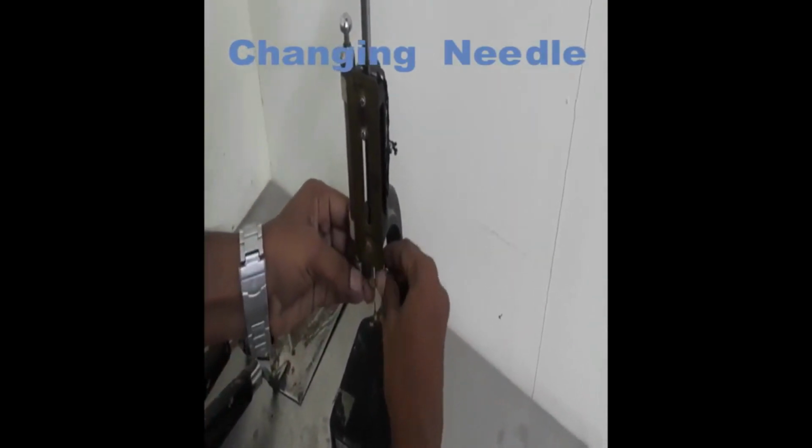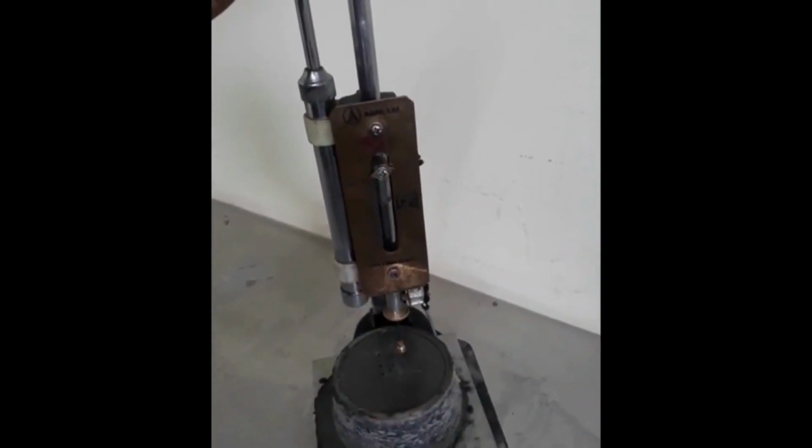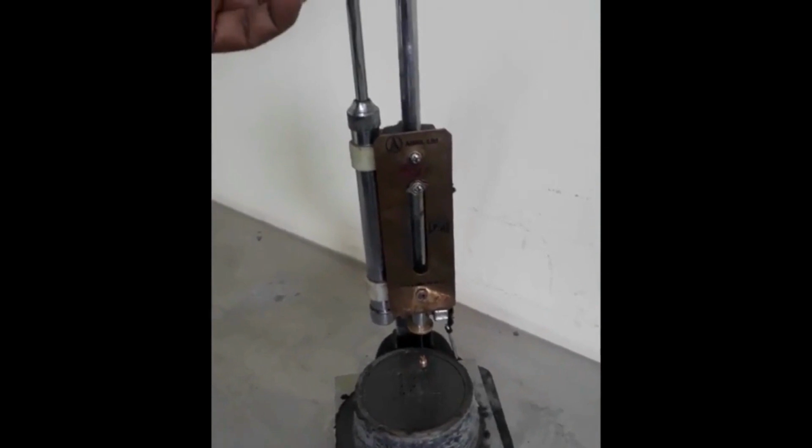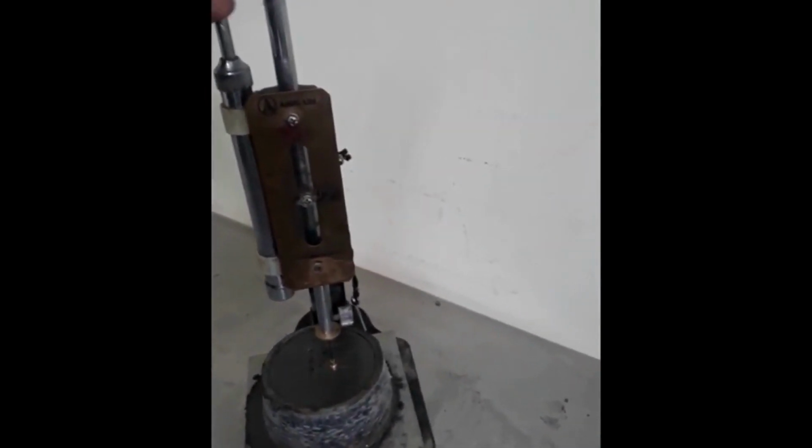So here we are changing the needle. This is the 1 mm diameter needle which is used for the initial setting time. Initial setting time is the time from the beginning of adding the water to the cement to the time when the penetration is equal to a depth of 33 to 35 mm.